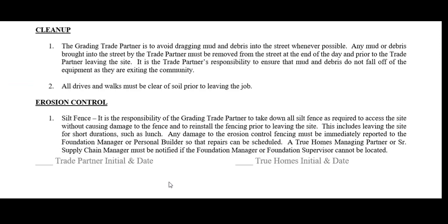And then you have silt fence. It's the responsibility of the grading trade partner to take down all silt fence as required to access the site without causing damage to the fence, and then reinstall the fencing prior to leaving. Any damage to the erosion control fence must be immediately reported to the foundation supervisor or personal builder so that repairs can be scheduled.